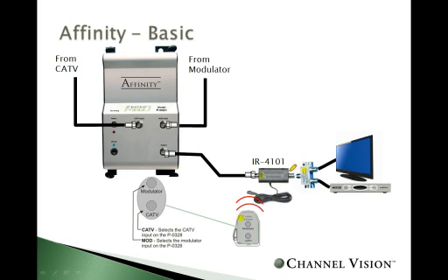People ask, well, what channel am I modulating on? Well, if I can't modulate on the digital cable spectrum because it's just too crowded, what this allows you to do is split the signal, going to the television's tuner and to the tuner of the cable box. We're actually modulating on channel 65 with our modulator just like we used to, except we're modulating on the television's tuner, not the tuner of the cable box. Simply switch inputs and you can see your cameras. No need to run a second line, no need to use a filter or make things more complicated.